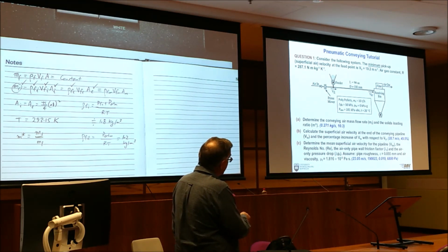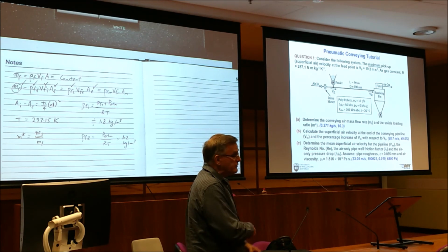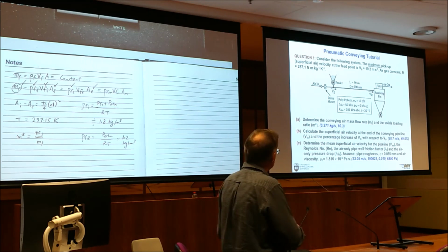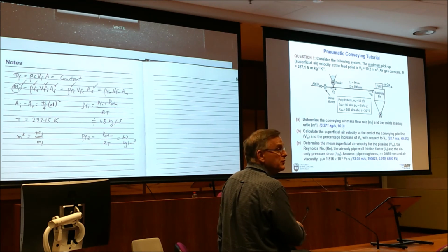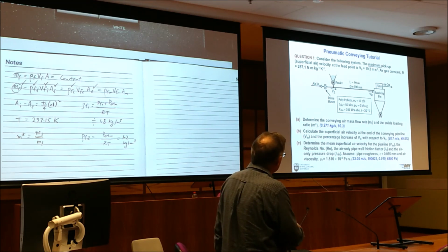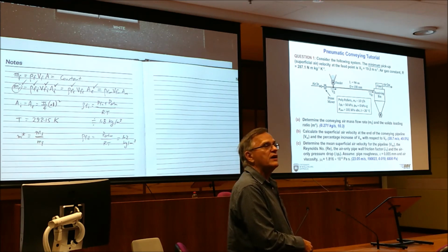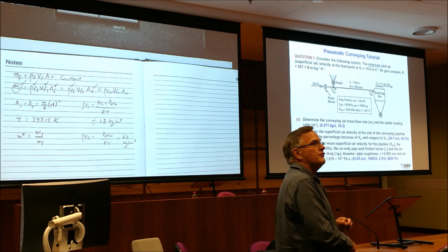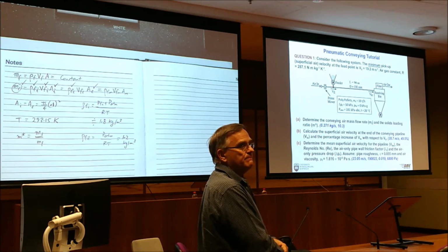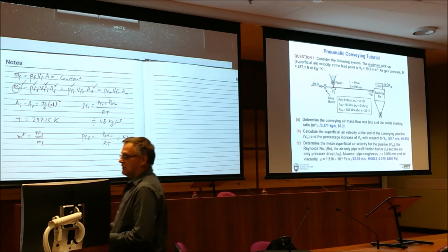You can then work out your Reynolds number, and the Reynolds number is constant through the system because it's isothermal. That gives lambda F from your Moody diagram. You've got the Moody diagram in your notes, so you can use that one. Then you put your numbers into the equation on the previous slide and you should get 6,800 pascals, using SI units again. Alright, so that's question 1 completed. And that's about it. I'll only take 1 minute for question 2.